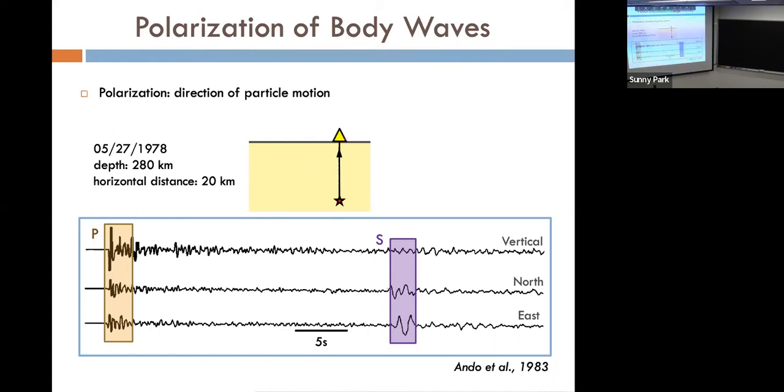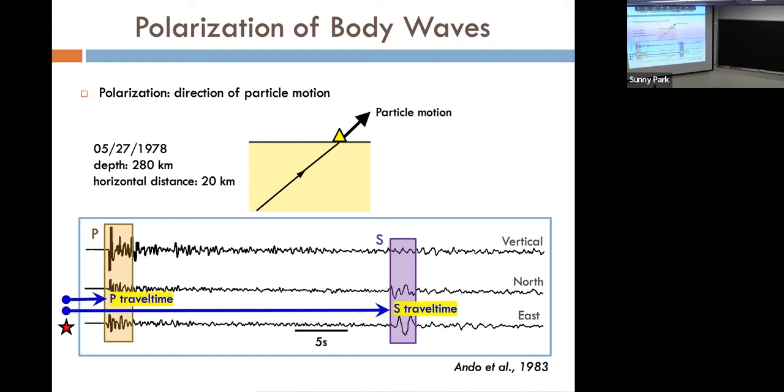And in general, the earthquake would actually come in at a certain angle, and I would be measuring this particle motion, and that's basically becoming my data. So if I were to summarize this whole talk in 1 minute or so, what's happening here is conventionally, seismologists, we would like to measure the travel time of the P wave and S wave from the earthquake time and use that for imaging the structure. But here, rather, we're looking at the directions of this particle motion, and that becomes really sensitive to shallow structure. So that's the point here.